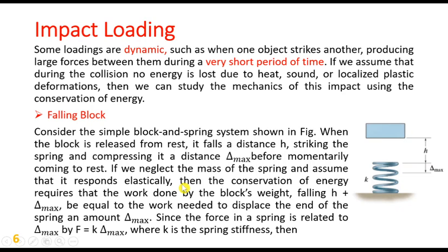Now, a very small, easy topic, impact loading, as the name suggests. It is for a very short period of time and it is dynamic, not static. Some loadings are dynamic, such as when one object strikes another, producing large forces between them during a very short period of time. If we assume that during the collision no energy is lost due to heat, sound or localized plastic deformation, then we can study the mechanics of this impact using the conservation of energy. So the law of conservation of energy will be used when there is no loss.